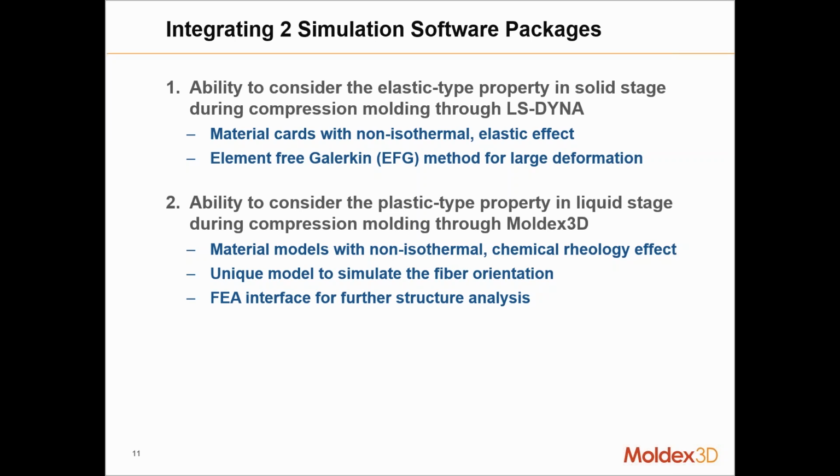So from LS Dyna, the material cards with non-isothermal properties are brought into the flow simulation software, Moldex 3D. Then in Moldex 3D, those initial conditions will be read in to calculate the final compression, which turns the material into a liquid flow stage.